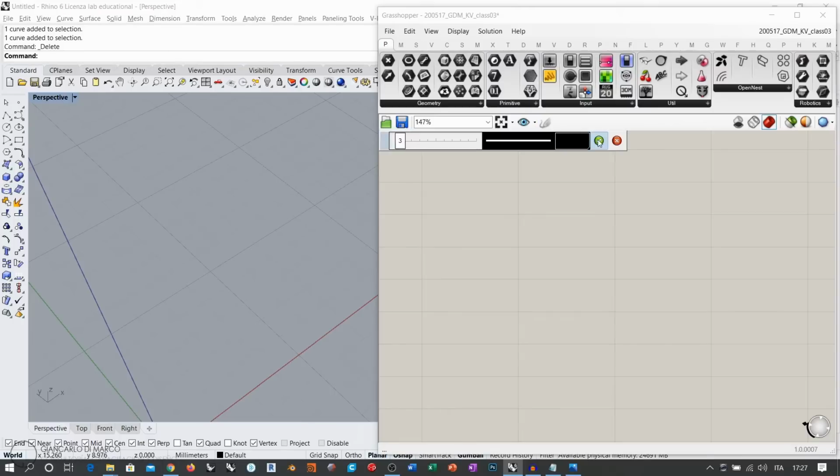and therefore we must change to a different mesh representation, which is called the half-edge representation. Why is this a better approach? Well, first of all, half-edge mesh representation is based on triangles. So we are only considering meshes whose polygons are triangles.